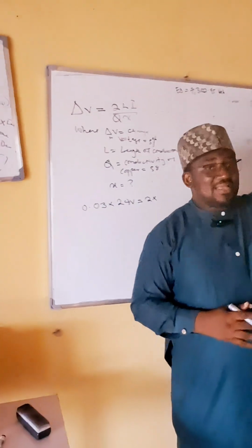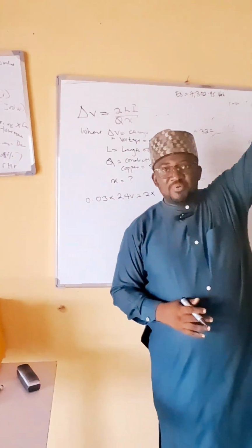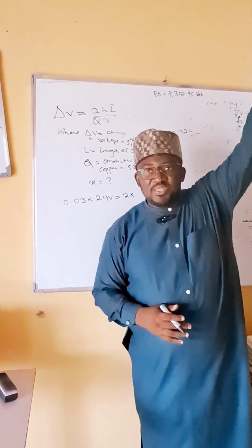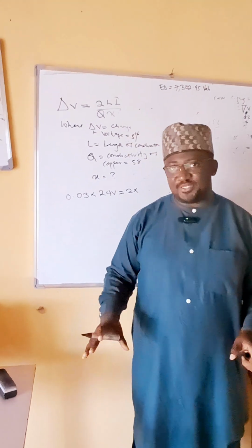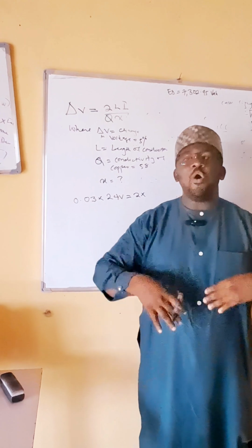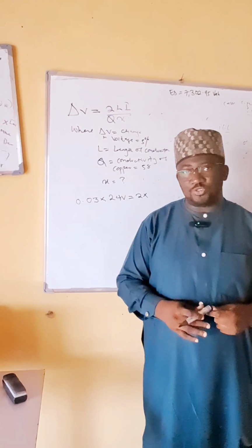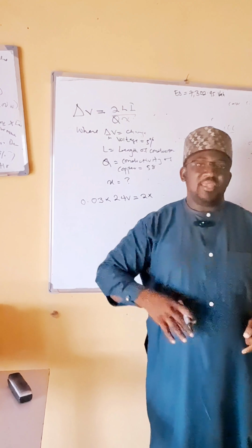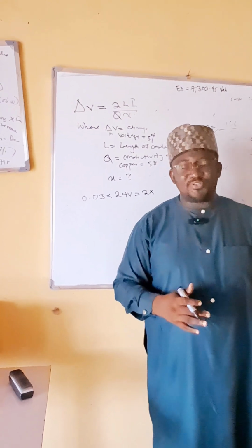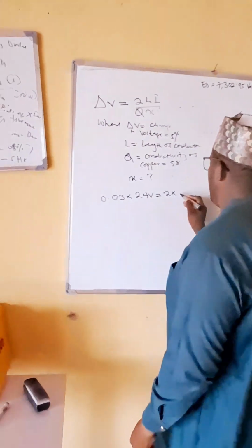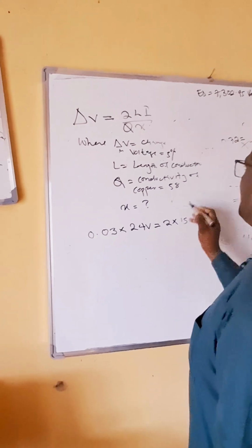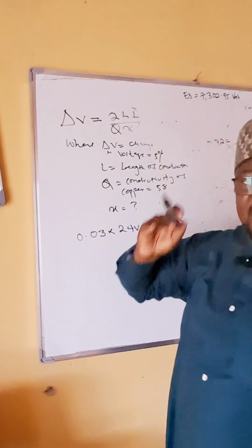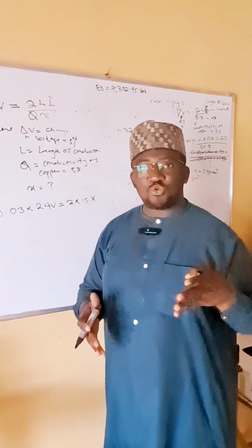We have to consider the cable connected from the solar panel downward to the battery, inverter and charge controller. How many meters did we measure? If, for example, we obtain 15 meters, then we say times 15. And then I is the current, which is the IMP obtained from our solar panel.